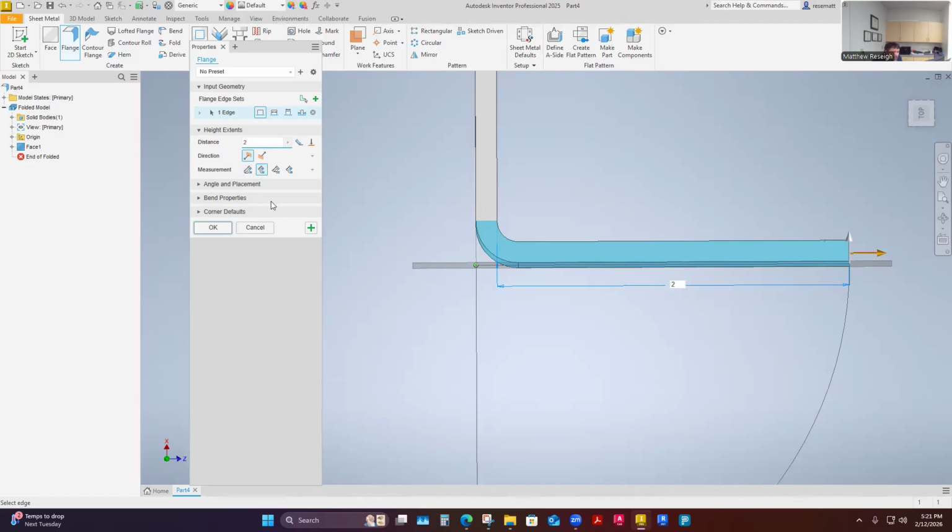So anyway, what we're dealing with is where the measurement of the part is. Is it OD? Is it ID that my 2 inch flange is measured to? Usually this matters. This definitely matters. There's generally a reason why one is going to be used over the other. What I want you to see is that if I unfolded this like origami, straight, one is going to need a longer amount of material to make that bend and meet those dimensions, and the other might be a different length. So this affects overall part length.